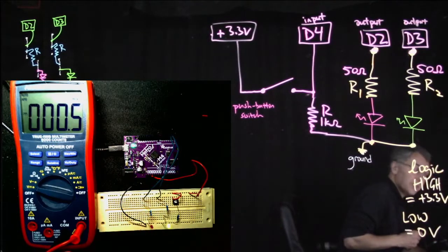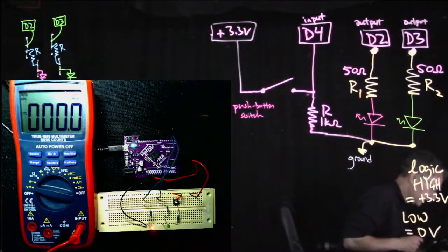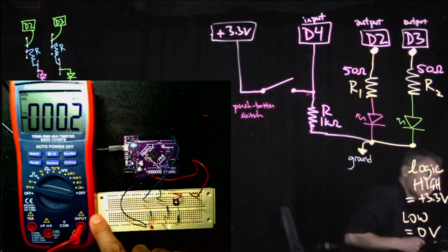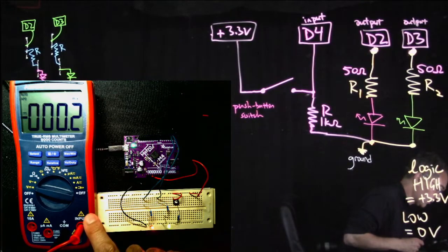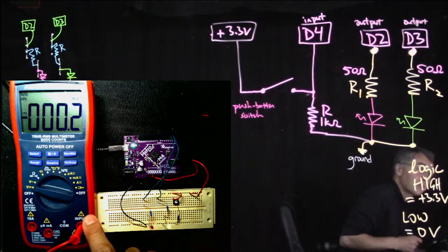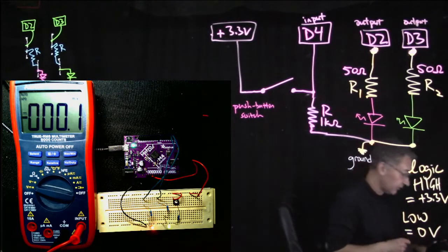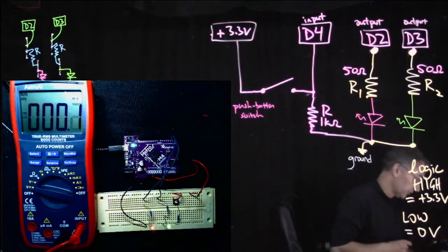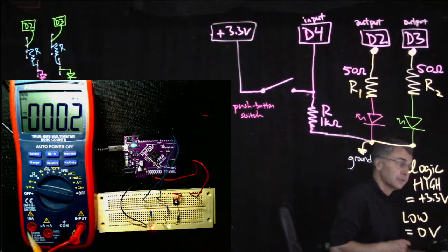The black wire is plugged into this thing labeled common. It has a little ground symbol. The red wire is plugged into this little thing called input, which is the input that you use for measuring voltages or for measuring resistances. It will turn out, if you ever use a digital voltmeter to measure currents, that the current inputs on a digital voltmeter are separate from the voltage input. So here's the input for voltage or resistance. These are different inputs for current. We won't use those today.